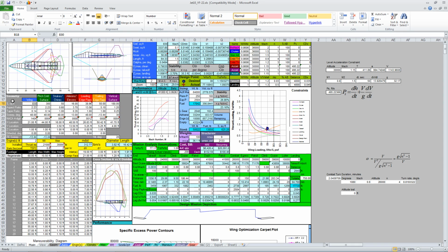So we'll start by eliminating that giant pitch control surface that allows the F-22 to be so maneuverable. We will not type a 0 in the area. We never do that in Jet. It messes up some of the ways some of the coefficients are normalized if you set a surface area to 0. So instead we just make it very small.